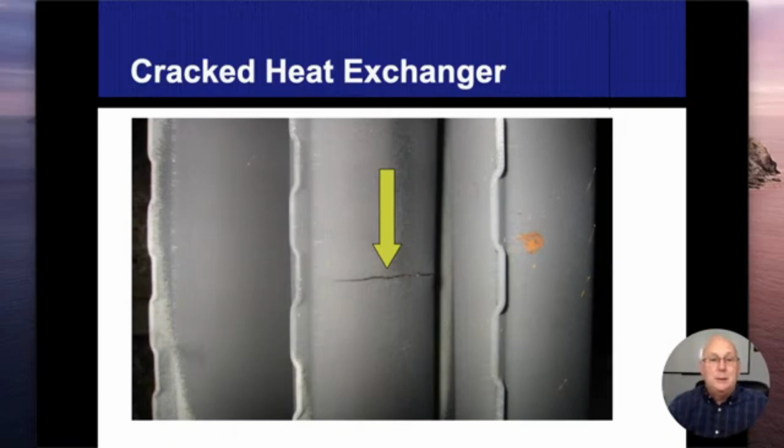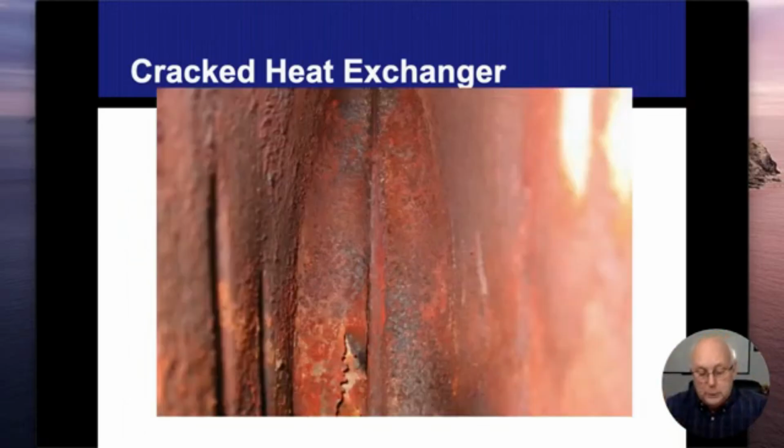All right, so this is an actual crack in the heat exchanger. We're actually looking at 3 dangers. Even though that crack looks very small, when it heats up, the crack opens up, and then where it is, it's going to blow in or out. All right. This one's kind of a no-brainer. If you can't see it, it's down here at the bottom. I didn't make a good circle, but that opening down there is rusted through.